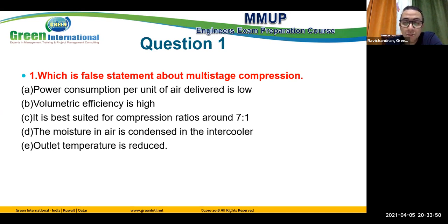We use multi-stage compression if you remember the curve for constant pressure. The constant pressure curve is close together from the left side and far from the right side, correct? This is the profile for constant pressure. So it's good here for the turbine expansion to obtain more expansion, and here to decrease the compression range. We need also more advantage for that, so we are going to use multi-stage compression. Multi-stage compression, we use this to decrease more the range for the compression.